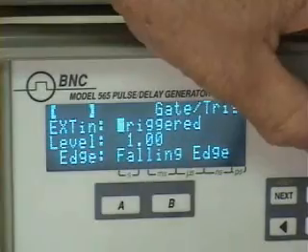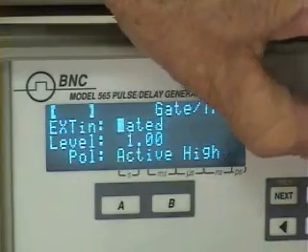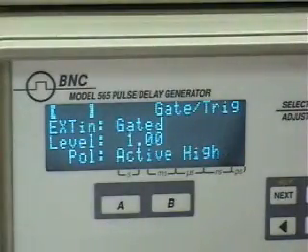your device mode. And if I turn the device once more, it says that I'm in the gated mode, and this gated mode tells you what level and what polarity my signals will be gated at. As you recall from the previous discussion, I can gate the individual channels selectively. So channel A can be gated, and channels B, C, D, E, F can be not gated. So that's something I can control, and that can vary from experiment to experiment.